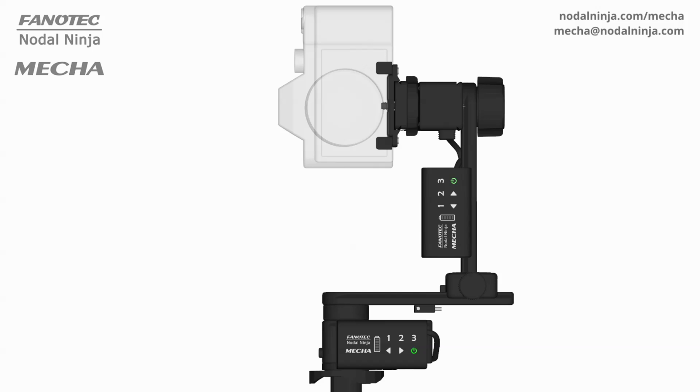A MECHA dual-axis combo, or MECHA DAC, consists of two motorized rotators and two C1 controllers wirelessly connected. The horizontal MECHA is also known as MECHA H, and the vertical MECHA as MECHA V. After both units are powered on, or when the power button is pressed, you will notice that MECHA H has the middle LED lit up green, and MECHA V has LEDs 2 and 4 lit up green. This indicates that the units are paired and MECHA V is connected to the Wi-Fi network of MECHA H.